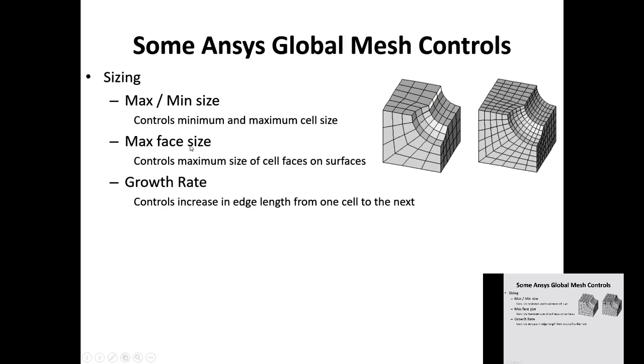And when you mesh, a very good practice to do is mesh the faces first, and then mesh the interior. Okay, so if you take this one as your domain, you take the surface. You mesh the surfaces first. So this surface, that surface. So you do all the surfaces first, and then you can do the volume inside afterwards, because you need a good